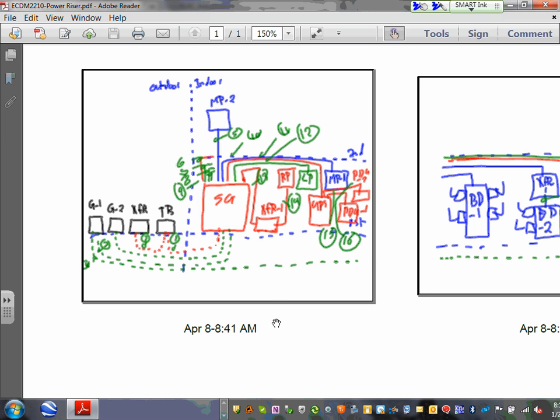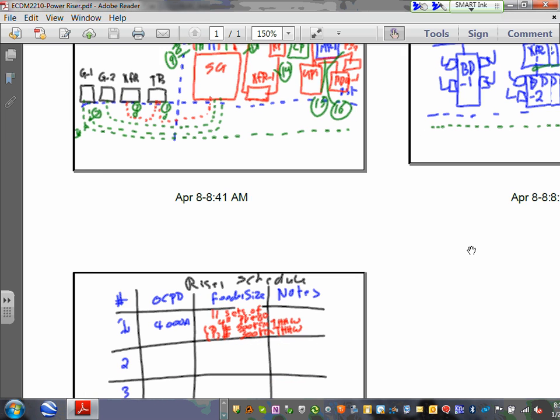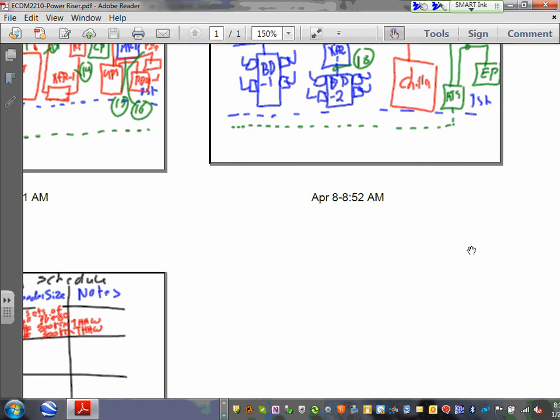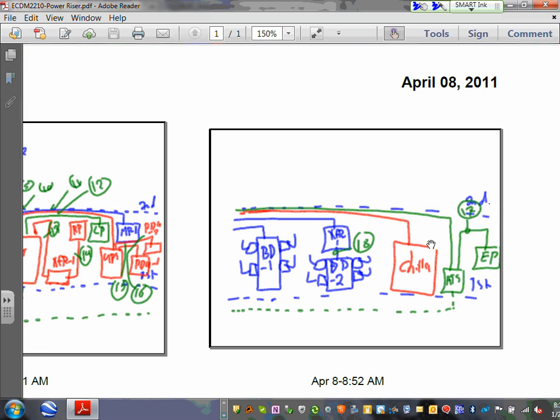Okay, how do you get that one to show here? There you go. Perfect. Then you're going to come over here. This is continuous also bus duct 480, bus duct 2A through a transformer. We have a chiller that we need to feed, and we have a transfer switch that feeds the emergency panel. That's how the system is built. If you guys read through the description, you should read it too. It tells you that's how you're going to build your system, basically, when we're building a system.